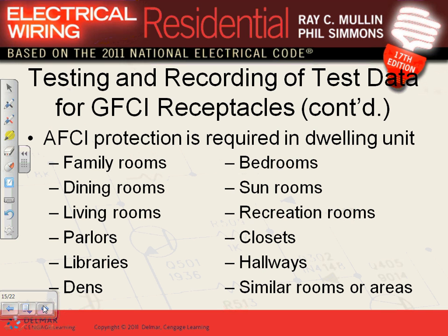Here's the location. This is a really nice place summarizing the locations for arc fault circuit interrupter. We went through it and highlighted in the code, guys. Basically, think of it as any place that doesn't have GFCI. Do I need arc fault circuit interrupter in the garage? No. Outdoor? No. Unfinished basement? No. Bathrooms? No. Kitchens? No. What else? Crawl space? No. Attic? No. Any question, guys? Any question about that?